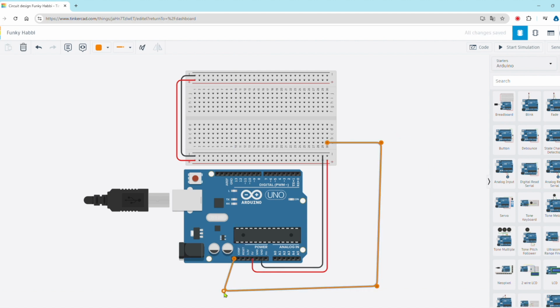The graphical format can be modified through the small circles that make up the cable path. You can explore and familiarize yourself with the placement of cables, which as you can see is assisted because it detects all the points where the cable can be connected graphically. At any time, you can delete the selected element. To do this, you can use the delete key on your computer or use the trash can icon available at the top.